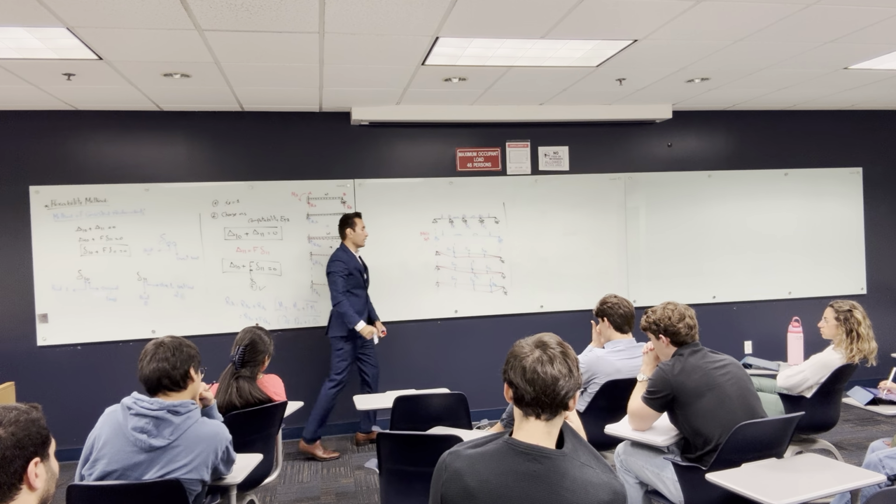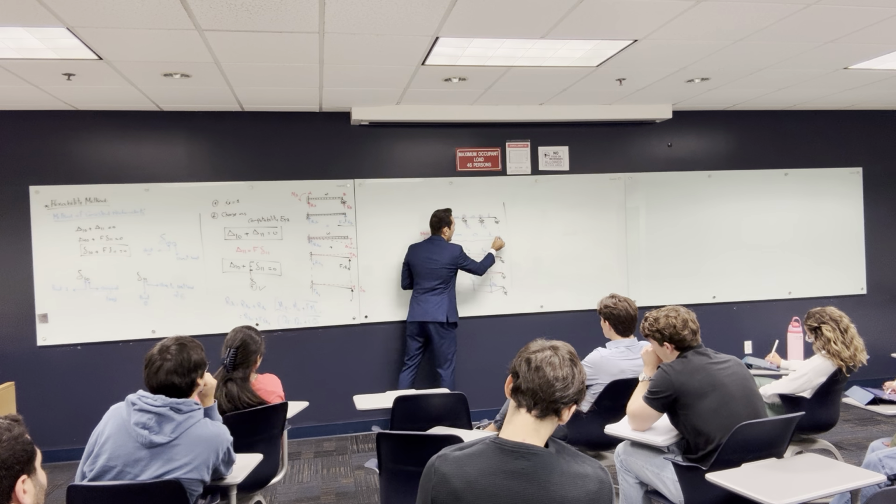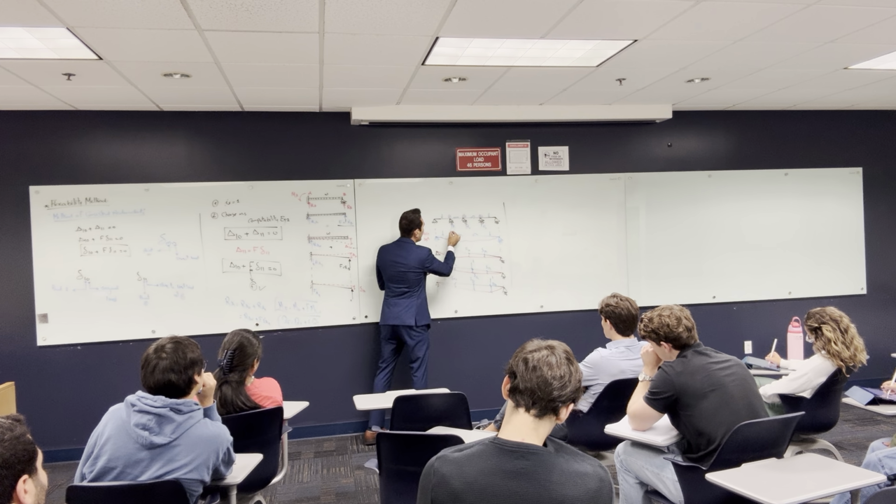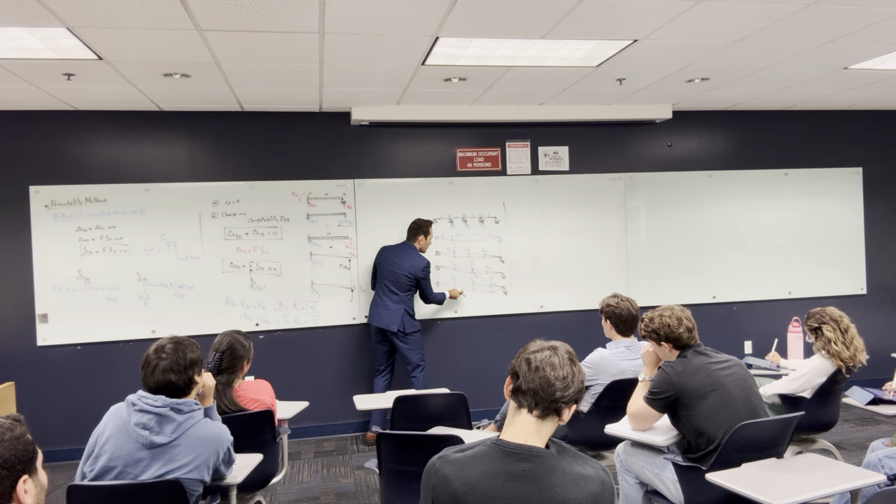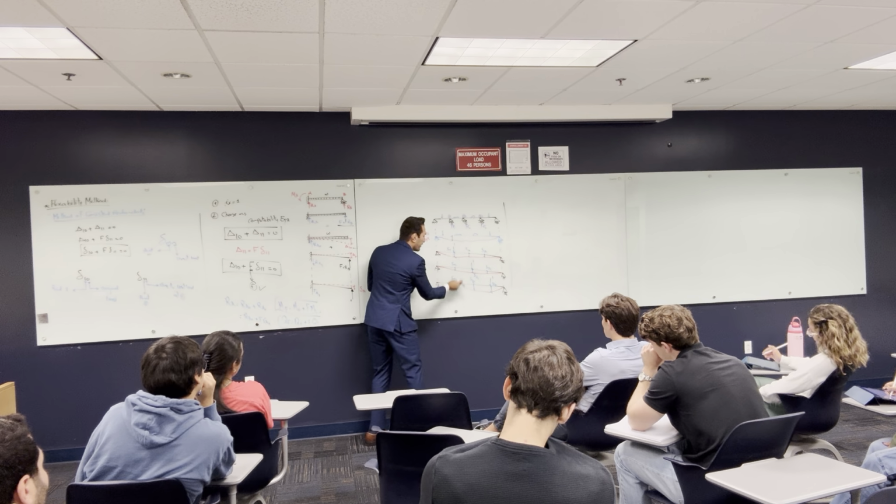Okay, let's see the compatibility equation. The thing is, at the end of the day, this is not 1. This is supposed to be F1, and this is supposed to be F2, and this is supposed to be F3. But I put 1 because it's much easier to solve. At the end of the day, the delta that happens here from the original loads is something like this, all right? So the delta that happens here should be countered by the 3 deltas that happen here. And by the way, you will see that all of them are in the same direction, but at the end, you are gonna get negative forces.